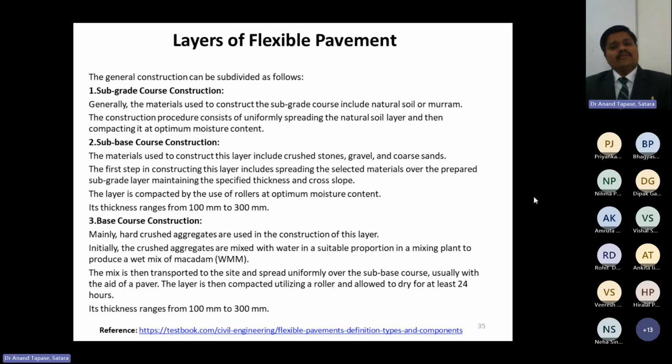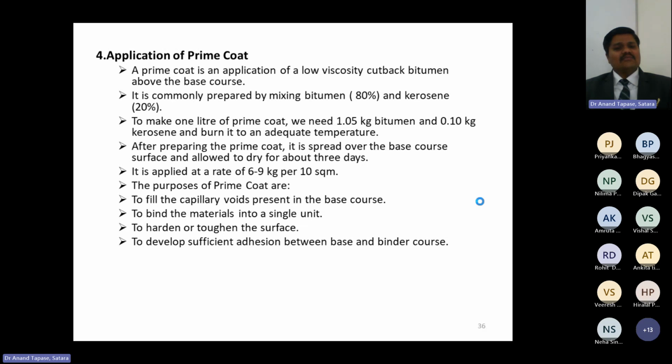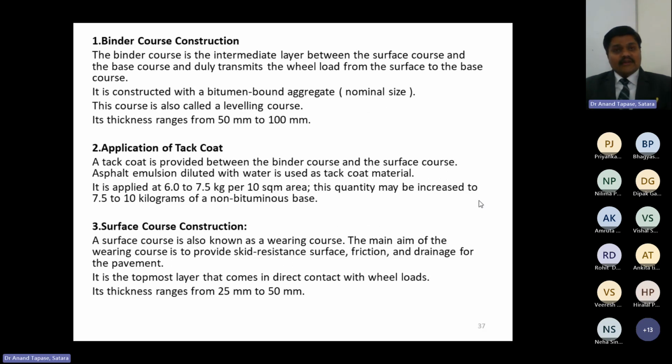Well, flexible pavements have different layers, starting from the bottommost, that is the subgrade course, then the sub-base course, the base course, and there are some layers like DBM, SDBC. Above that, we consider the bituminous concrete, asphalt concrete. So the layers are different, out of which the design consideration considers only three types of layers. The topmost layer is the bituminous layer. Next to that is the layer constructed with murum. In a number of cases, the terminology we use is grade 1, grade 2.